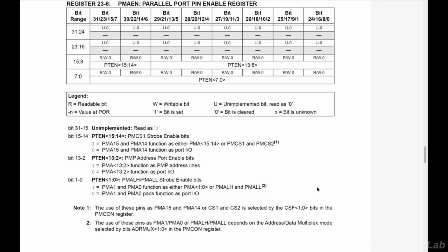If multiplexing is enabled, it operates with this, and if it's disabled, as in my example, then it operates as an address pin. So we want address A0 all the way up to A15. So we get our full 16 bits, and then we have to bit bang other bits all the way up into, I believe, 19.